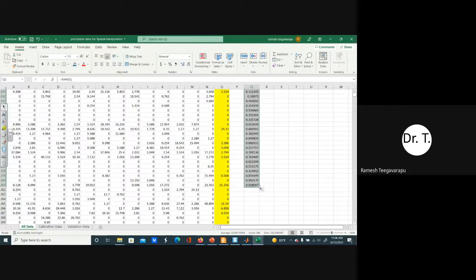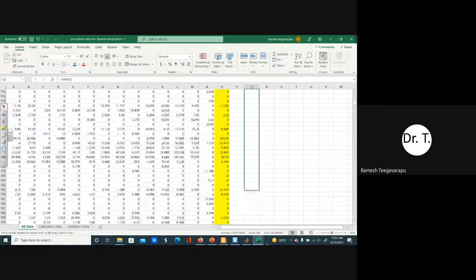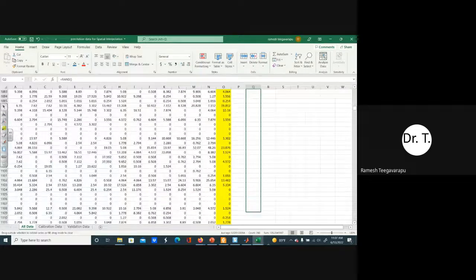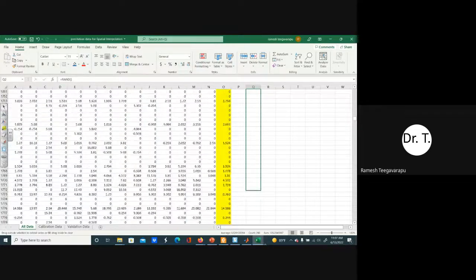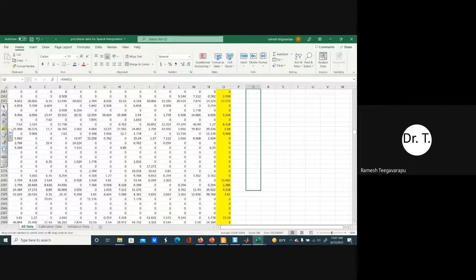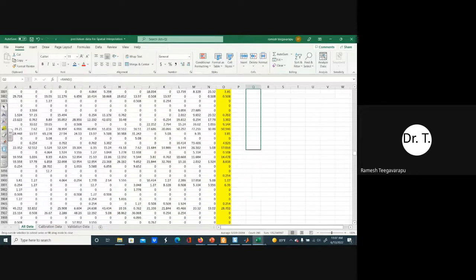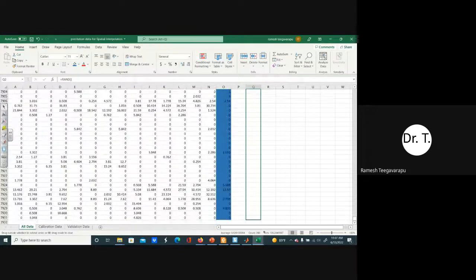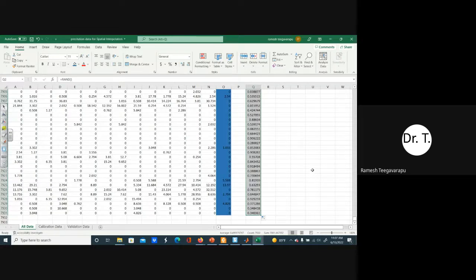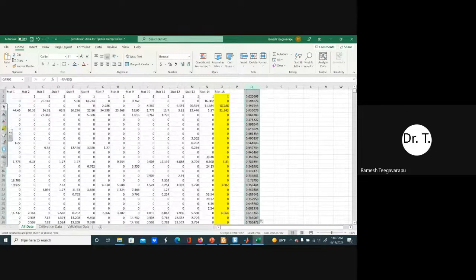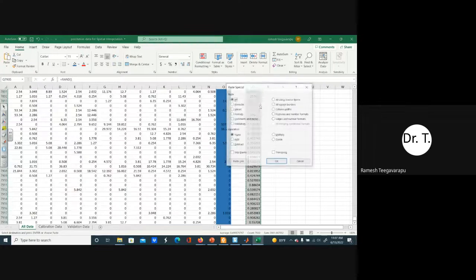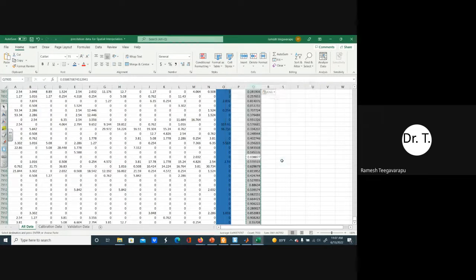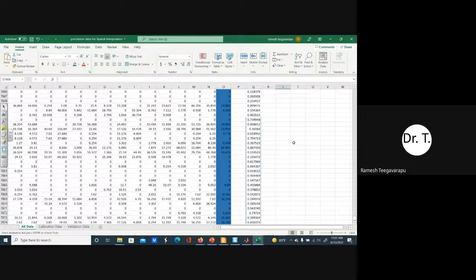Okay. So basically what I'm doing is I'm generating a random number which will be between 0 and 1. So I'm using what we call pseudo random numbers, because a computer cannot generate real random numbers. These are pseudo random numbers, but that is fine. They will do the job for me. So I basically generated random numbers, and because Excel changes every time I change the cell, I'm going to copy it and then paste it again as special so that the values will remain there.